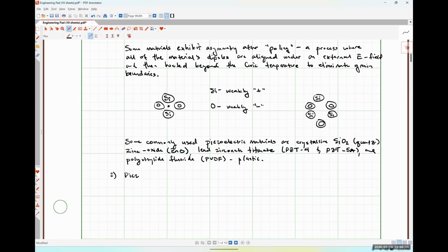Piezoelectric materials are self-generating, okay? So what I mean by that specifically, when we looked at piezoresistive sensing, for example, we always had either some sort of bias voltage, typically a DC bias voltage, or some sort of DC bias current, and our output signal was proportional to those input voltages and currents, right? If we went back to our notes, we would always see there was a term of I_DC or V_DC in the signal that we were looking at.